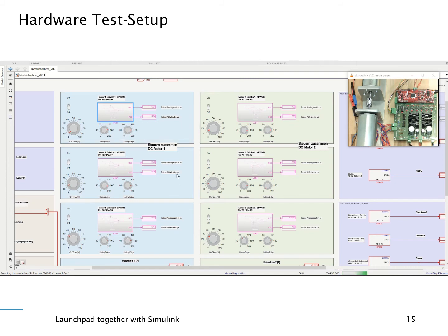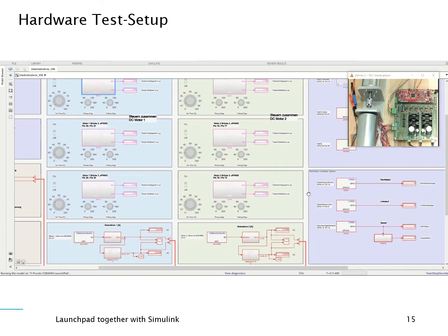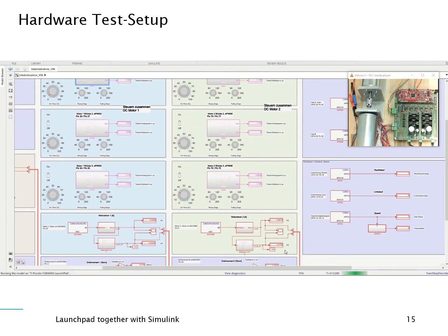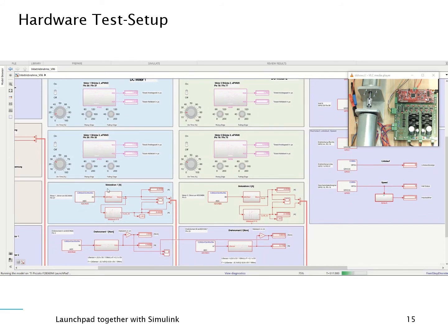Then, like I said, for this example we have 6 half bridges applied within the circuit. So, of course, I need 6 of these half bridge control EPWM blocks. For the rest of them, I read ADC values for the current of motor 1, current of motor 2, and so on.